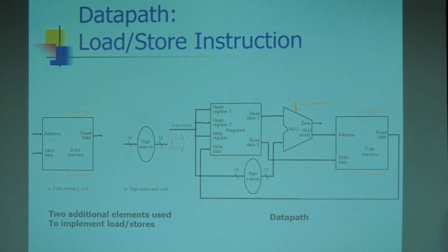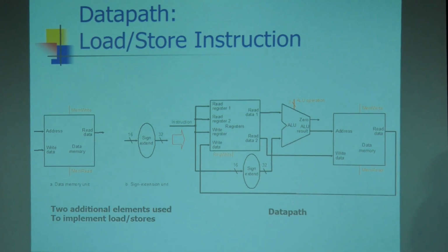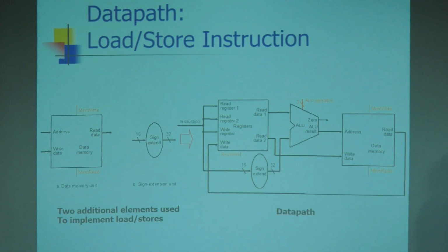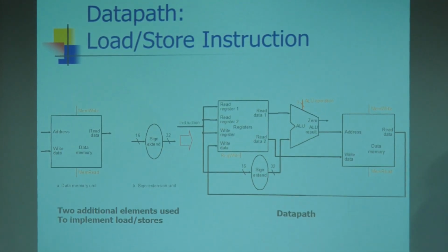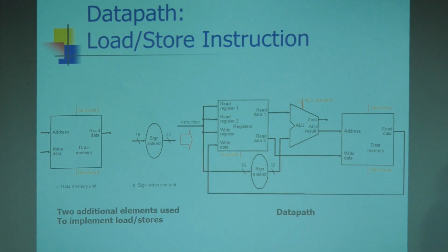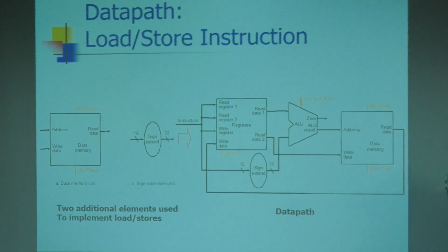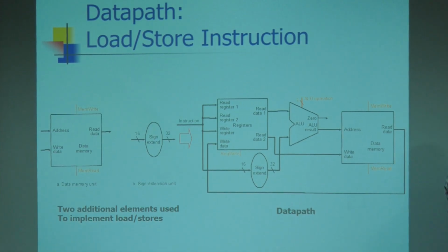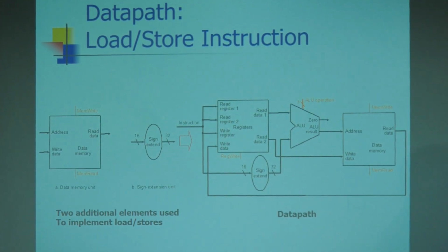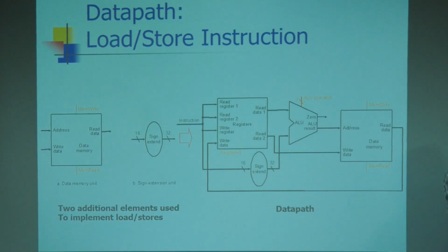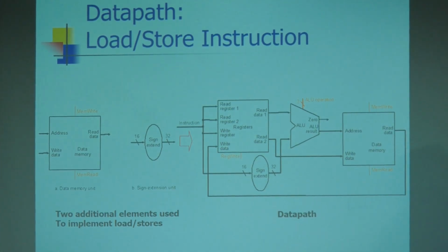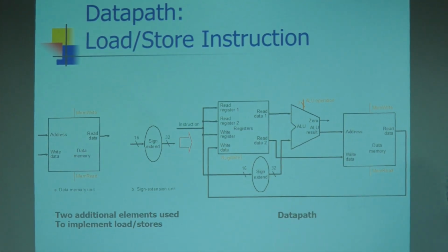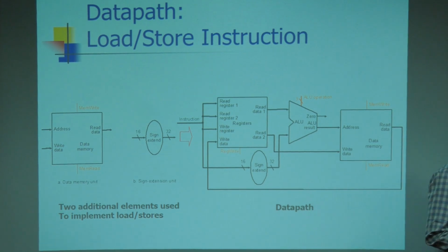So we can read and write through a separate read signal and write signal, or otherwise. The read signal is 1 when reading, or 1 for a write operation. With separate read and write, the number of input and output pins is decreased in memory implementations. So we have address inputs, control inputs, and data for read and write.